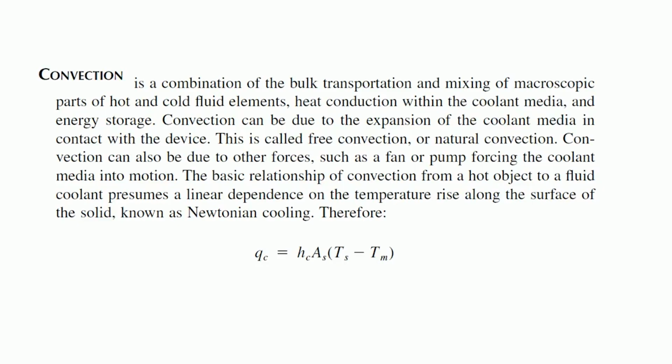Now, come back to my slide. Convection can be due to the expansion of the coolant media in contact with the device. This is called free convection or natural convection. So, what happens here is buoyancy is set up. The moment something expands, the density comes down and immediately it will try to rise up. This is the basis of natural convection, which is good. My body gets naturally convected